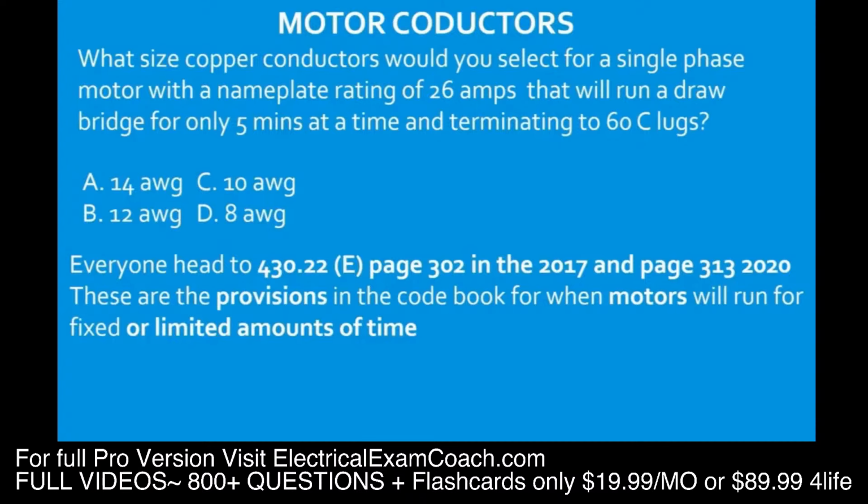So with that being said, what you're going to do is start on the left-hand side and find your situation, then come across the top and tee off with your amount of time. When you get that value, it's just going to be another multiplier. It's just another demand factor.